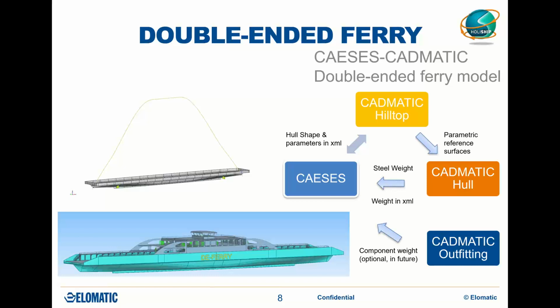These parametric positions can be given as an absolute coordinate or by, let's say, bulkhead distance with respect to other bulkheads or decks. Position of bulkheads and decks can also be defined with formulas. For example, the position of the fourth bulkhead can be derived based on required volumes in tanks or based on required car lane areas.